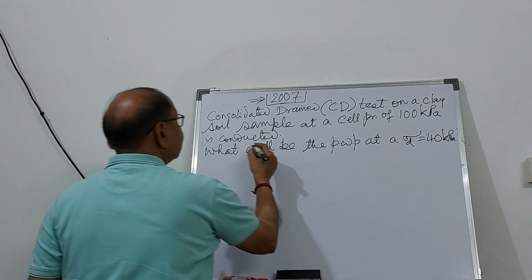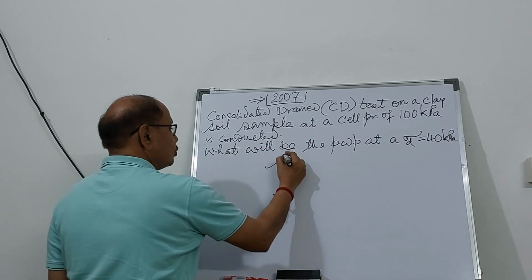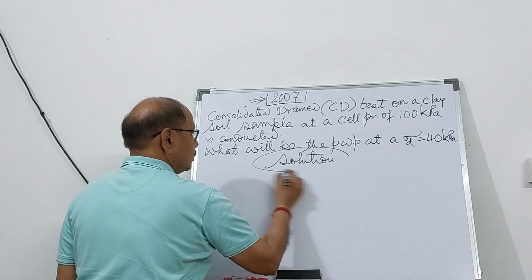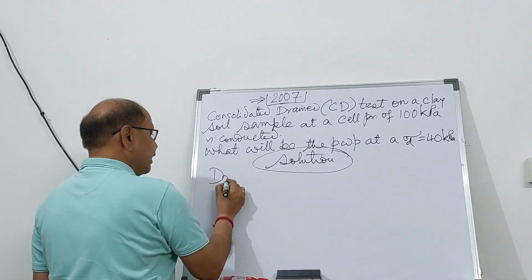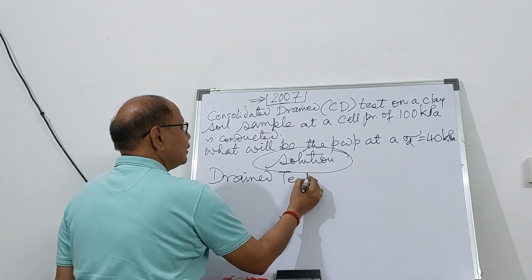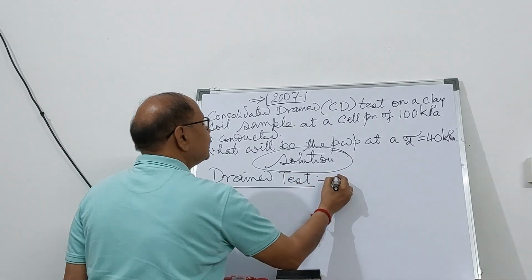Now look here, it is a drained test. So solution is quite simple. It is a drained test. And in a drained test, the pore water pressure dissipates.